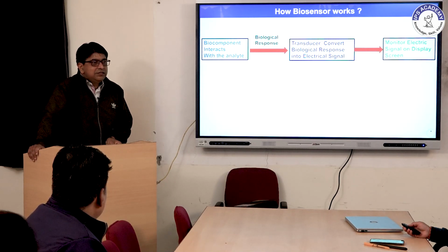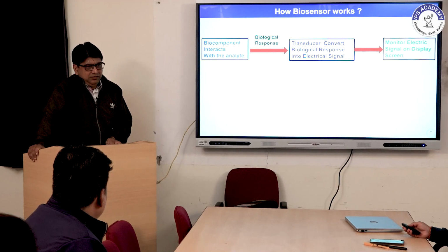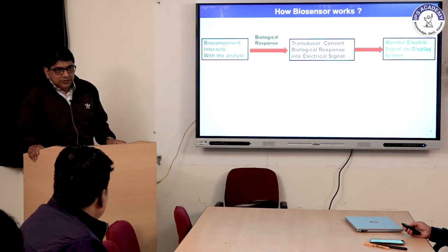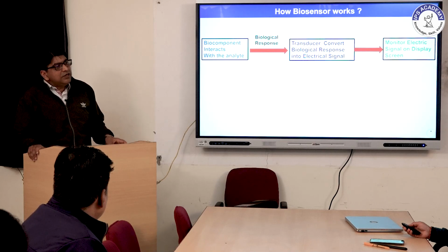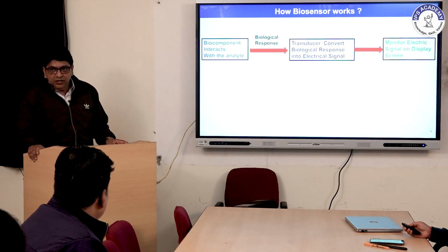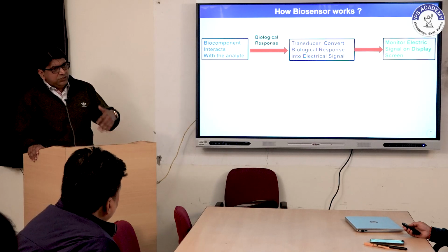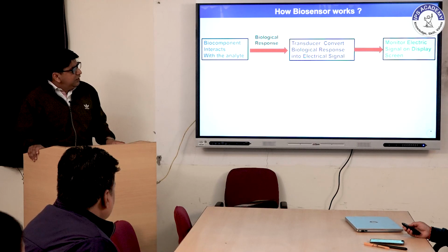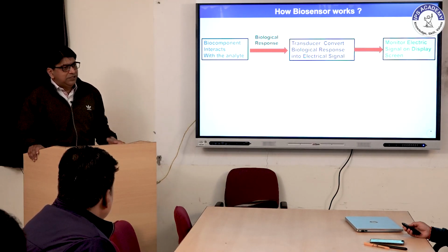The electrical signal is very weak in magnitude and strength, so we need to amplify it, and the weak signal will also merge with some noise. So we need to remove these noises. Some signal conditioning is required, and after that we have to amplify the signal. Then we go for the processing aspect, maybe with a DSP processor or a general purpose processor, and finally we have to display whatever things we are going to measure onto the measurement device.